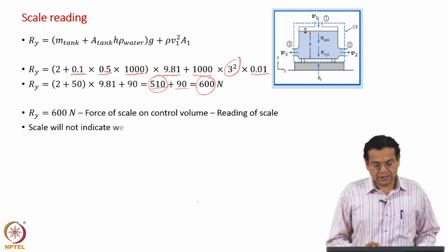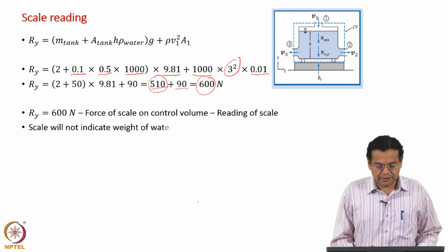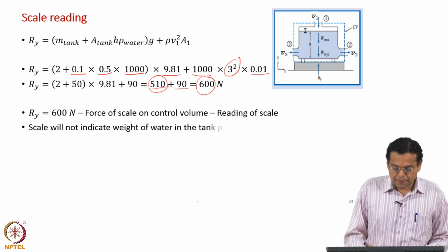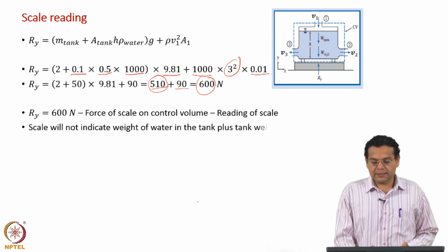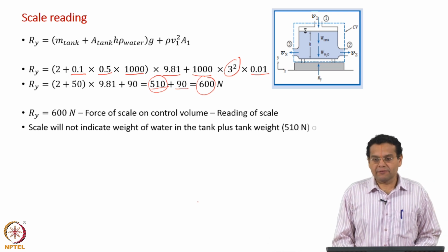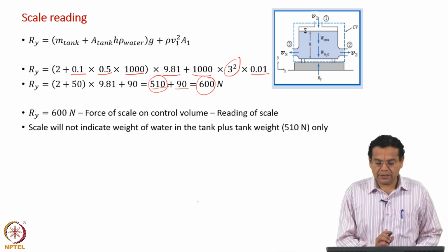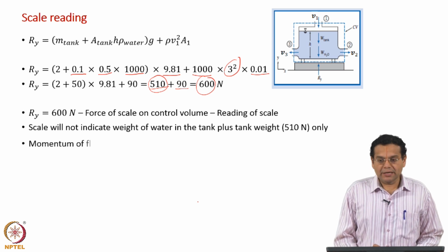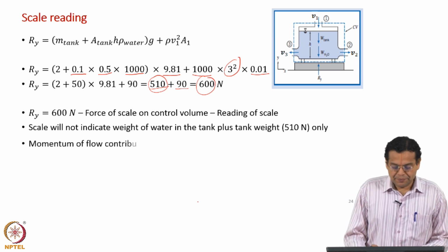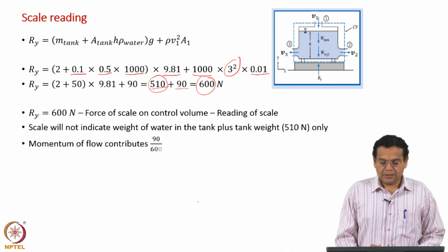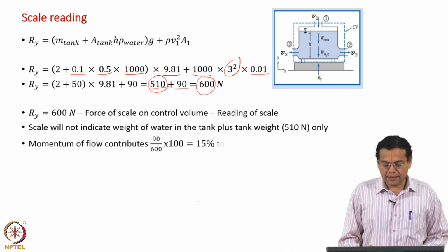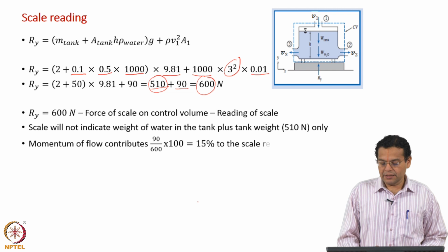So, to answer the question, scale will not indicate weight of water in the tank plus tank weight, that was the question, whether it will indicate that. So, it will not indicate 510 Newton only. Momentum of flow contributes 90 by 600, 15% to the scale reading.